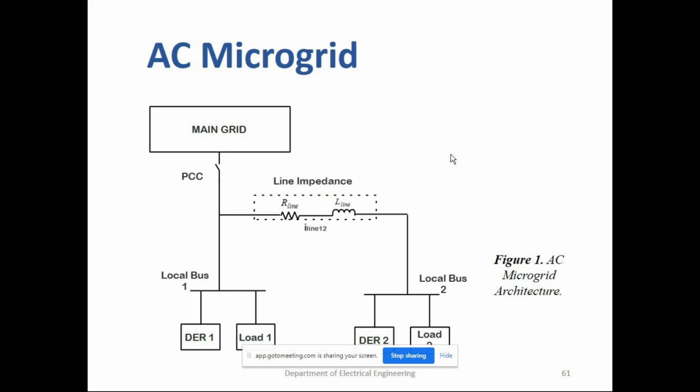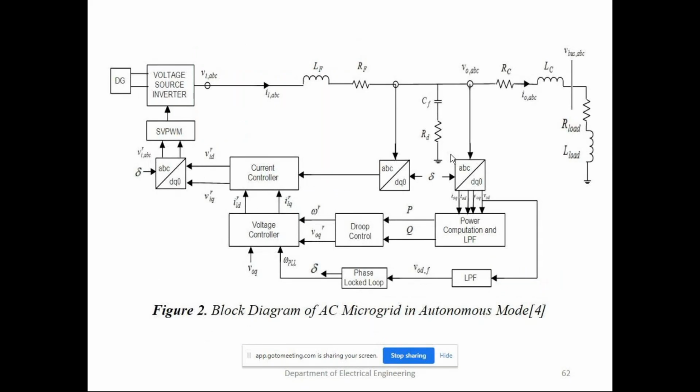You can go for the optimal power flow subjected to the different constraints. Now you see different power electronics converters are there, the dominance of the power electronics converters and its state space modeling. For that, for instance, I am taking this into consideration. This is the normal current control, and remember the current control loop is always faster than the voltage control, and you know the transformation and switching poles corresponding to the voltage source inverters, and this is your PCC, and you have the transformation of the same.